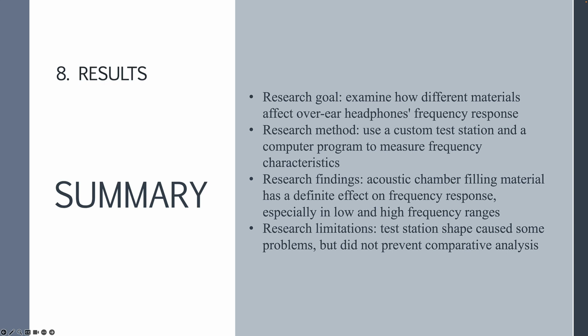Silicone non-woven reduced the sound pressure over the entire range to a similar extent and resulted in a smaller reduction in the time of impulse characteristics fade-out than the other materials. Cotton wool resulted in greater reductions in sound pressure values in the low 20 Hz to 300 Hz and mid 300 Hz to 3 kHz frequency ranges, and comparable to silicone non-woven in the high one. It also caused a faster fade-out of the impulse characteristics than the silicone non-woven.